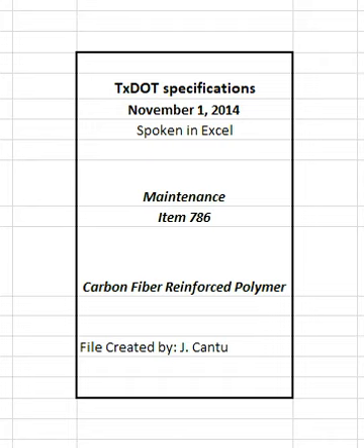Fill all voids or depressions of diameters larger than 1/2 inches or depths greater than 1/8 inches with approved material. Provide surface roughness requirements for strengthening as detailed in working drawings. Round or chamfer all inside and outside corners and sharp edges to a minimum radius of 1/2 inches. Remove all laitance, dust, dirt, oil, foreign particles, disintegrated materials, and any other matter that could interfere with the bond of the CFRP to the concrete using abrasive blasting.